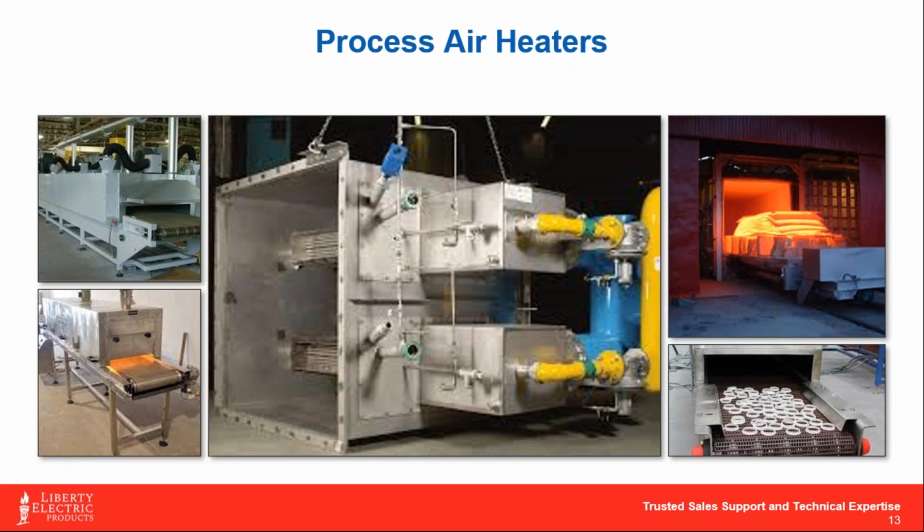I mean, if we were to look at something like Corning glass, that's an application where, yes, a gas-fired furnace is going to serve you a lot better when you're trying to heat up extremely large volumes of product. Electric air heaters, however, can also be extremely precise in their temperature control, which is a big attraction to these as well. They're excellent at maintaining within 1 degree set points versus gas units. So it's really more of an application-driven thing.